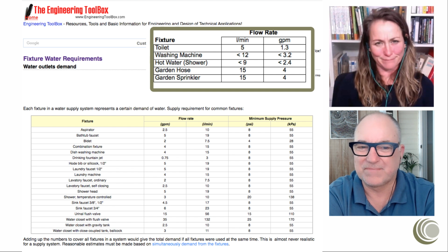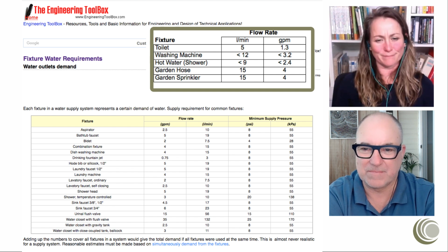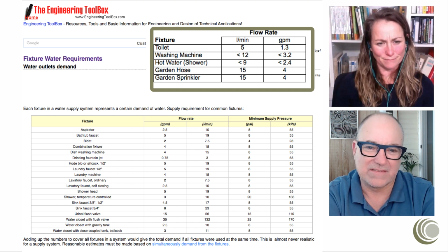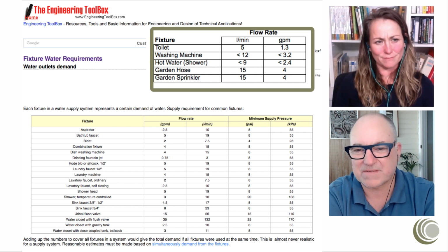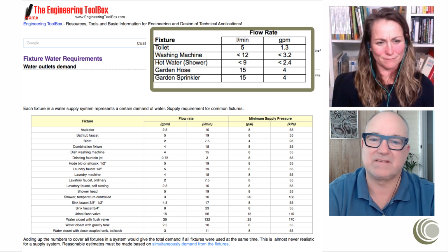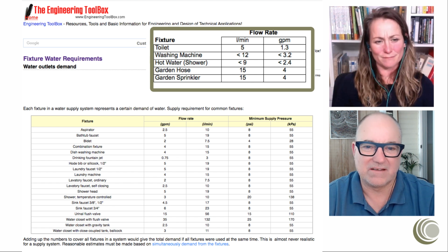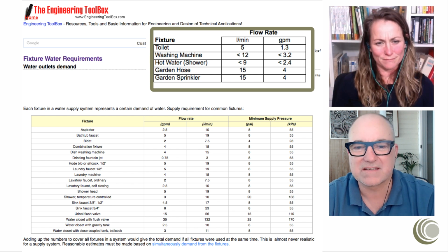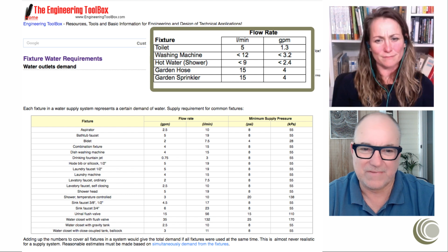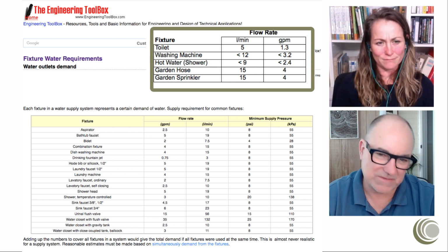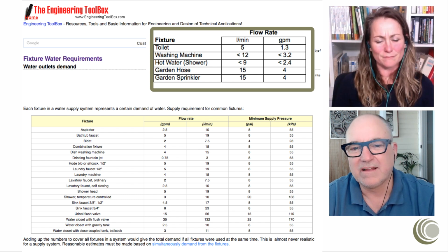And the pump pressure: the smallest pumps around, and they're not the smallest, but the most commonly used in the rainwater industry, has been around the 300 to 350 kPa. That's an external pump. If it's in the bottom of a rainwater tank, it'll be higher.